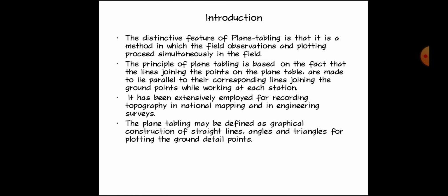The principle of plane tabling is based on the fact that the lines joining the points on the plane table are made to lie parallel to their corresponding lines joining the ground points while working at each station. It has been extensively employed for recording topography in national mapping and in engineering surveys.